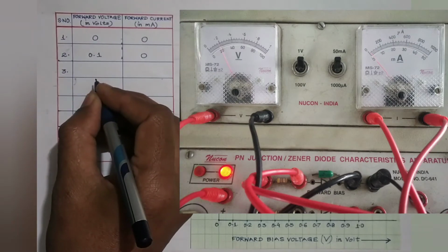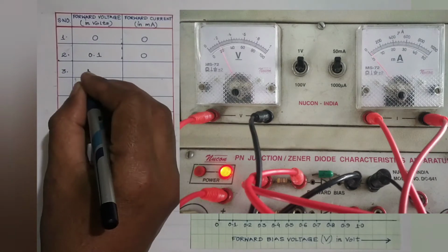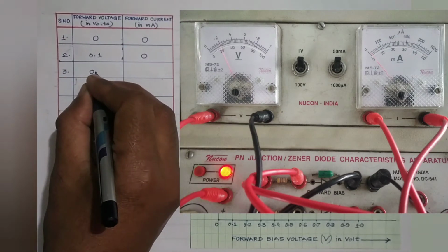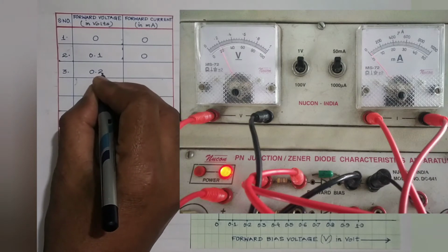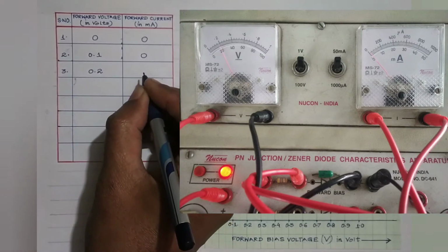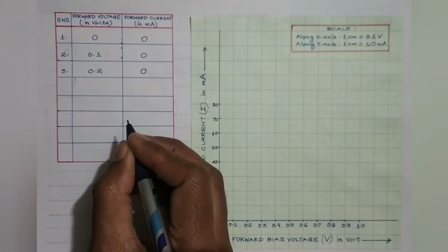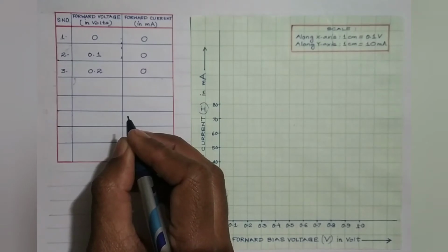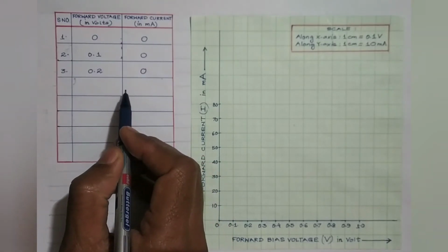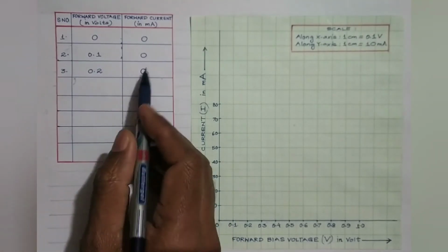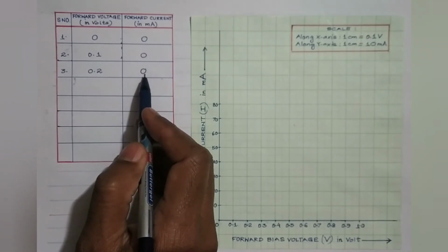If we keep on increasing the forward voltage in equal steps, now for 0.2 volt, again we do not notice any deflection in the milliammeter, so the forward current is 0. So we can notice that initially, as the applied forward bias is low, practically no current flows through the junction